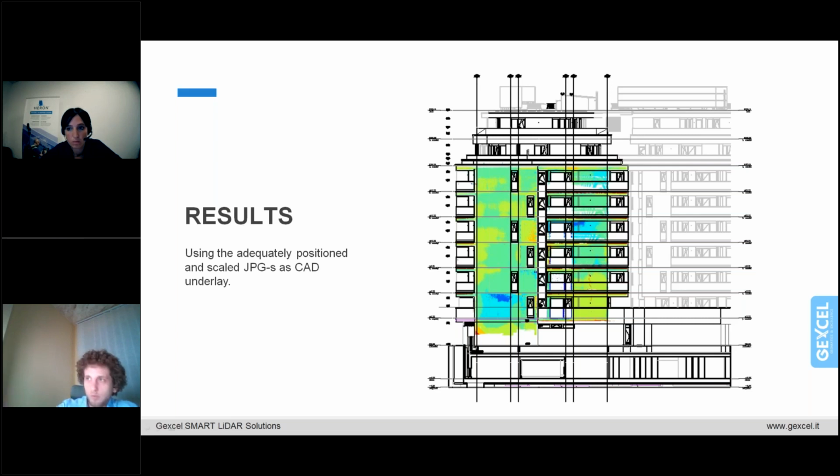So again, these kinds of cast concrete structures could be inspected with a total station, 2 meters per 2 meters, but you would never have the big image and the general overview of what happened and where the small out-of-tolerance areas might be.